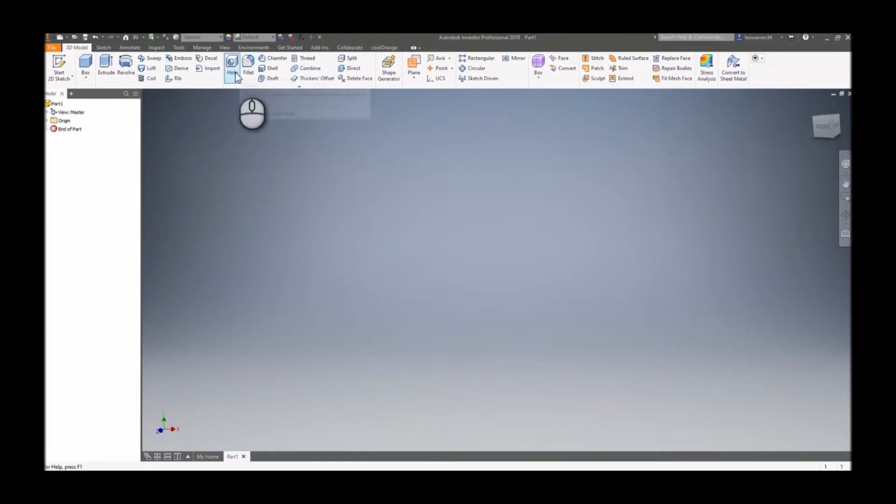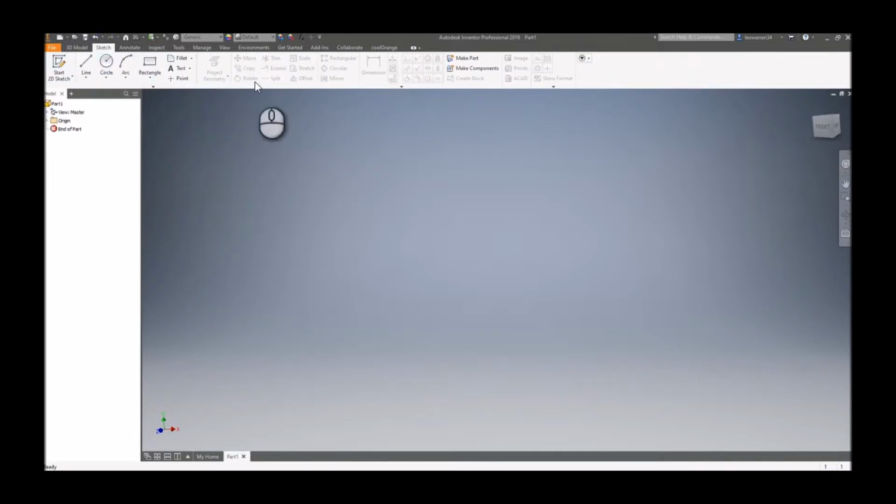Holes, these are a bit more of your specialist features. They're used to do your edges and holes, after features that you don't add to the raw geometry. Then you've got planes, axes, points, so these are for when you want to define other stuff, so you can start working at different dimensions, so you can offset stuff. And then we start going into actual surfaces and patch workspace, if you have worked in 360, and actual forms where you can start moulding around it. You can also go into FEA and stress analysis, and then you've also got sheet metal, which is a whole different part and assembly environment.